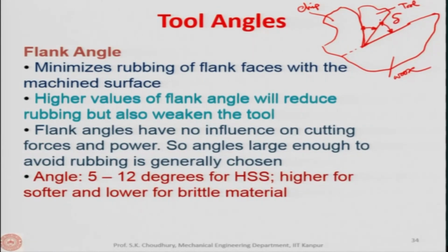If the value is larger, it will never rub off the work surface, so we are safer. But it should not affect the tool strength. We should increase the value of the flank angle only to the extent that the tool strength is sufficient for that particular process. That is the thumb rule.